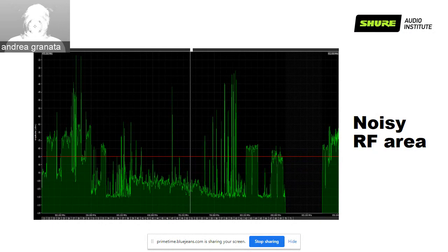Something that is just very difficult to understand where it's coming from. Typically, it may be LED screens, computers, or other digital devices around, but it can be even some AC power equipment. So it's very difficult to understand where it's coming from, how it's produced, and it's usually showing like the part that you see in the center of a scan without a specific carrier. Maybe it has some spikes, but they are not clearly recognizable. There is no pattern. This is the generic noise floor.